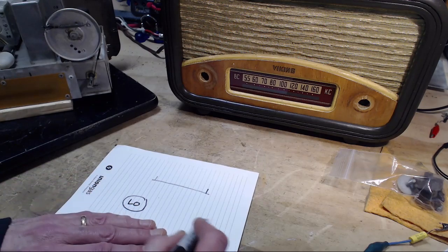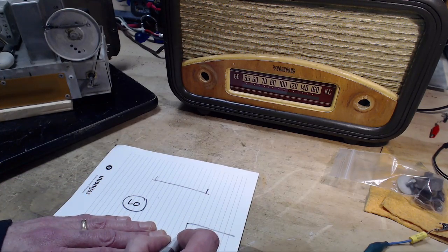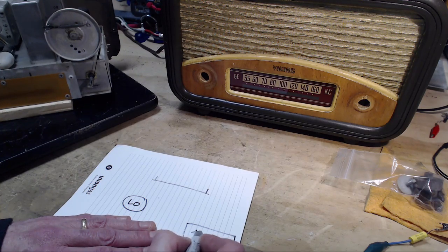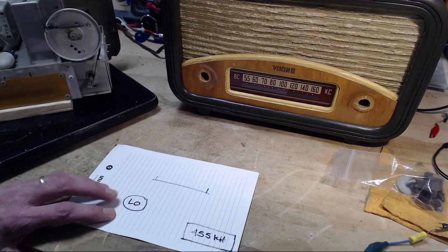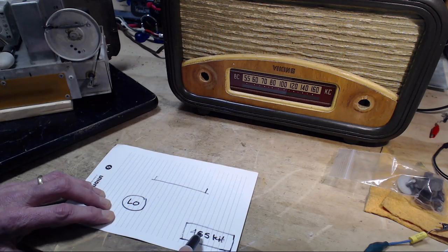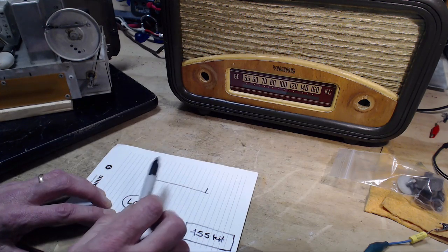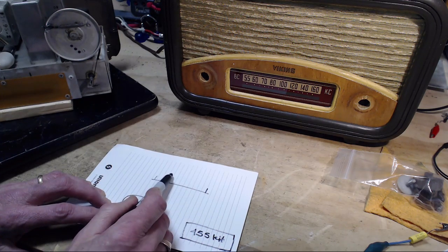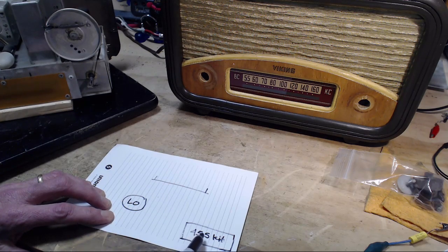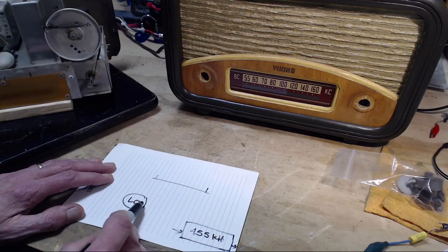And then we have an IF, almost like an internal radio built inside the radio that tunes only one frequency, normally 455 kilohertz, but it could be anything. But this is the standard, kilohertz. So the whole trick is to get the signal that could be anywhere in this range of 530 to 1600 and convert it to 455, where it goes through and comes out to the speaker, basically. And there's more going on here to get the speaker to operate, but that's basically what you're doing. You're using the local oscillator to convert it.